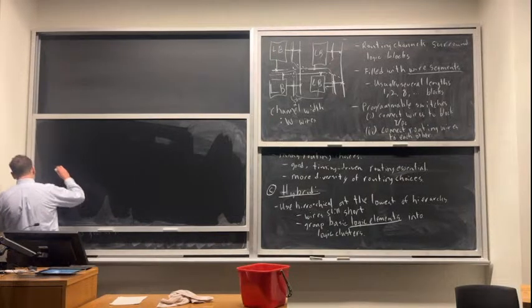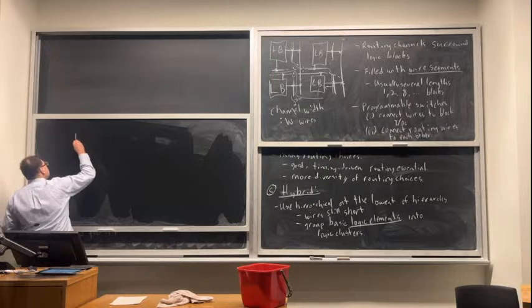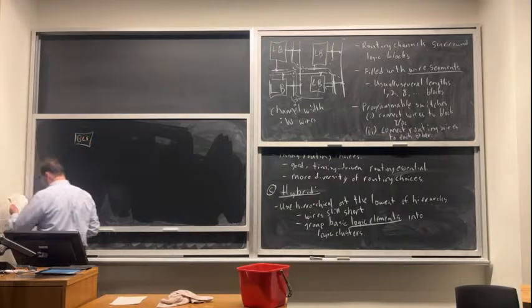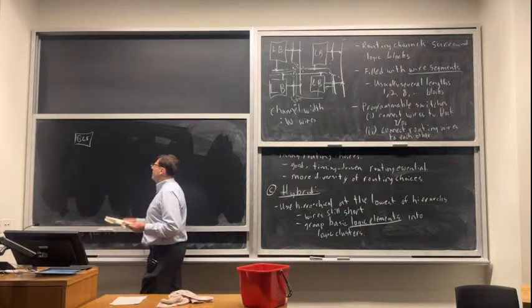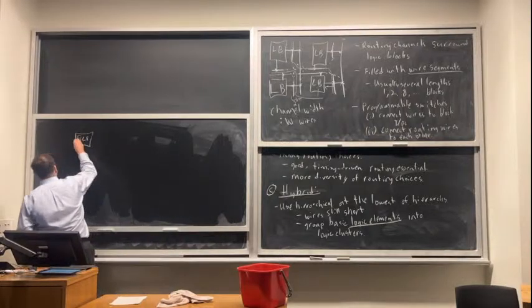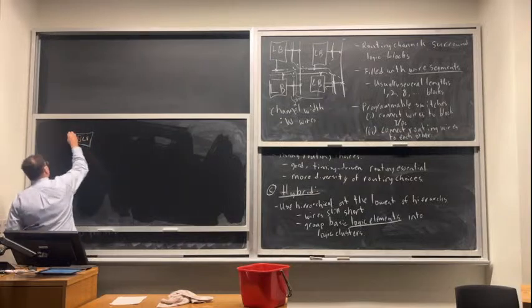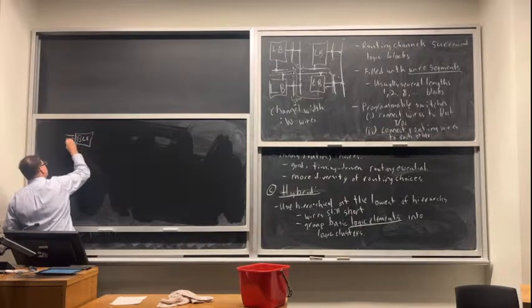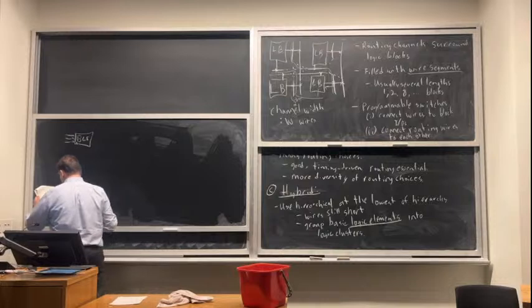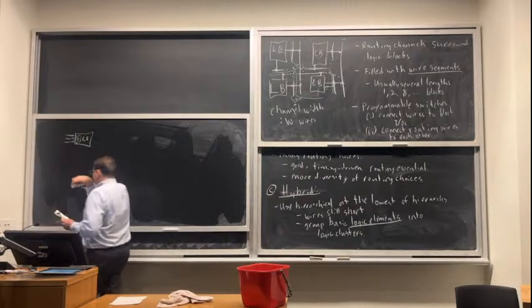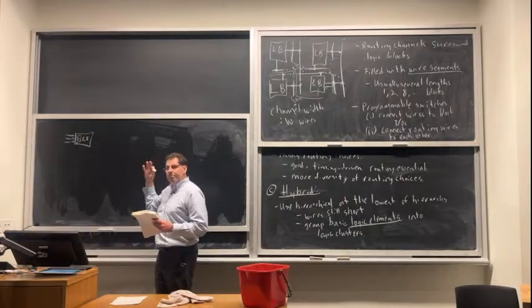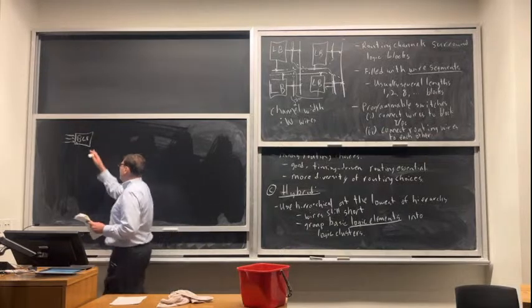Okay, so what does this look like? We've got a basic logic element, which is basically a LUT and a flip-flop. So it has a clock, and it has a few inputs coming in to go into the LUT. What Xilinx was doing, in its earlier architectures, was connecting this directly to the programmable routing.